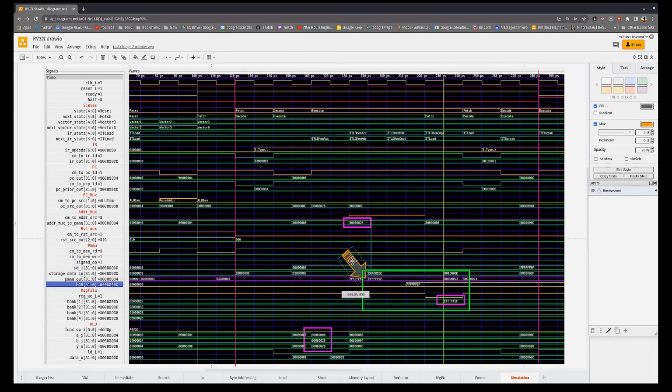So the function 3 would be 00. And so it saw that the EF that it's trying to load in, the lowest byte here, the bit is high because it's an E. And so it sign extended it out. And again, that's what we load into the MDR, which is then eventually loaded into the X1 register. So we've loaded a byte and sign extended it all into the register at once. So it doesn't say dead beef, it's a bunch of F's and then an EF. That's the load byte signed.